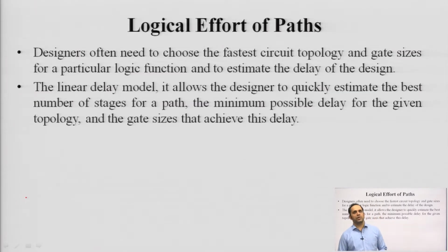So, from the designer's point of view, one might need to choose the fastest circuit topology with lowest delay and optimized gate sizes for the given logic function, so that you can estimate and minimize how much propagation delay is being propagated from the input to the output. The linear delay model, as discussed earlier, allows a VLSI designer to quickly estimate the best possible number of stages and the best possible path, such that the delay for the given application can be minimized.